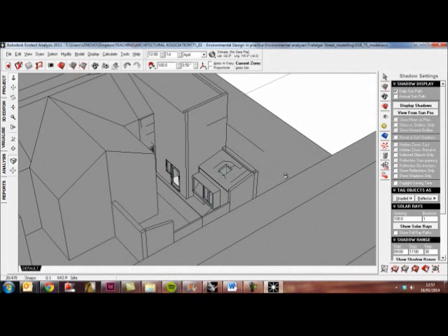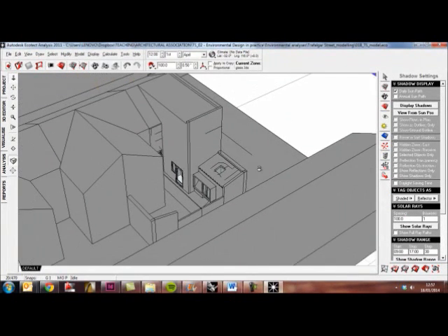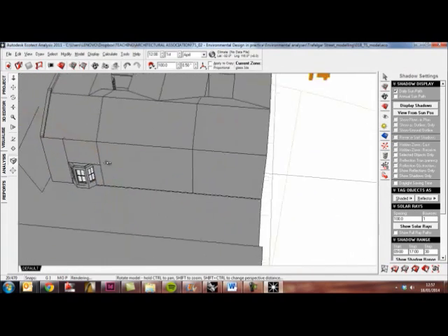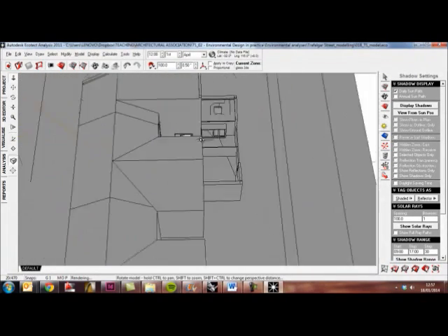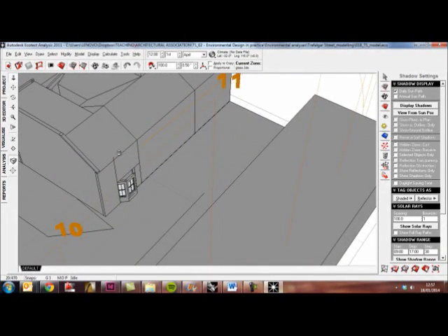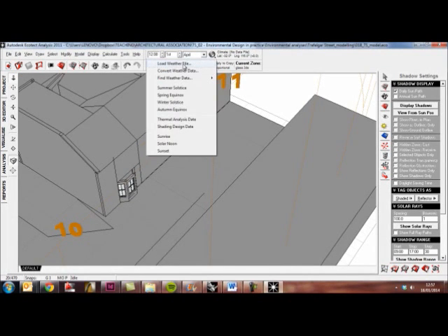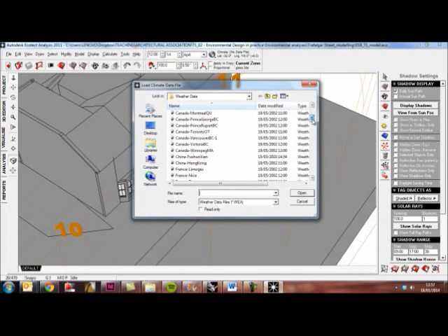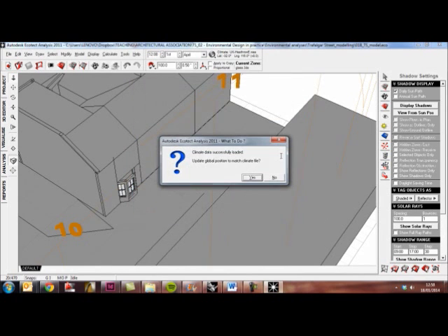The next very important thing we want to make sure we know is the orientation of my house. Orientation is going to be really critical in terms of the relationship between the sun and my home. So obviously we've got to get the climate right first. Ecotect always seems to import the southern hemisphere climate, Australia. I don't live in Australia, so I'm going to have to pick a climate which is relevant. So I'm going to go down to UK Heathrow. That'll do fine. I'll click that.